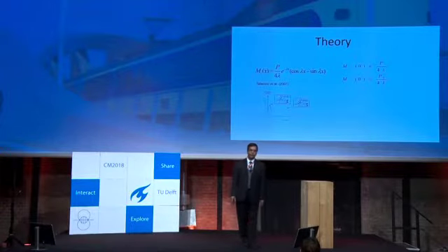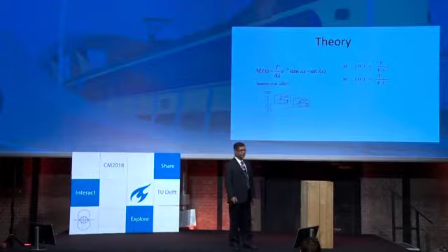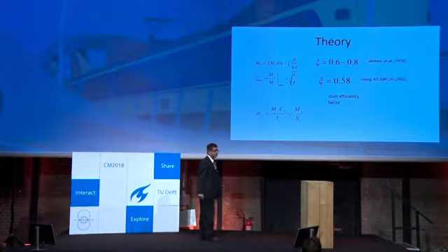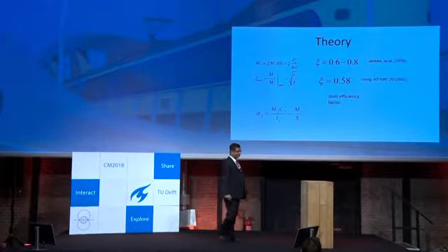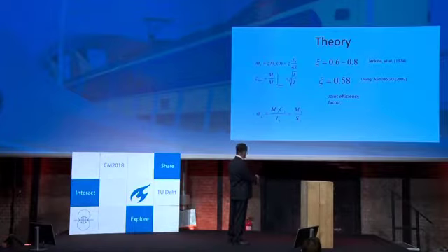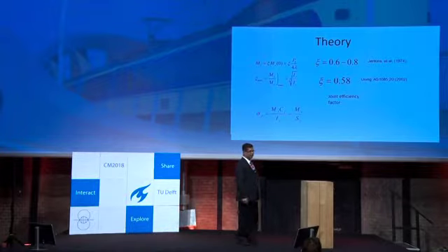Our talk is on the joint bar, so how can this moment distribution be transferred, or formulated, to the joint bar? That can be done by another factor, which is called the joint efficiency factor. If we multiply the moment distribution in the rail by this factor, we can get the moment distribution of the joint bar or fish fillet.